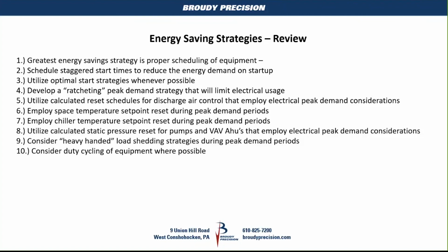So you can consider some heavy-handed load shedding strategies if you can get away with it. A lot of our facilities won't allow it. You can't shut the air handler off. The people will freak out, you know. I mean, you can't shut the pumps on a chilled water system down. The chiller will stop and we'll need a manual restart. But there are some things like exhaust fans for certain areas of the building. You might be able to shed loads that way.